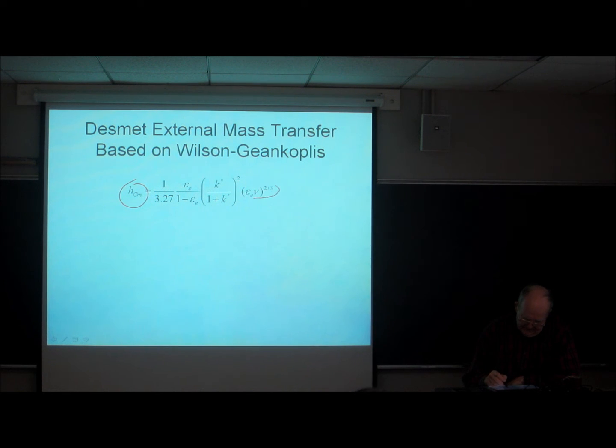And the flow dependence, the velocity dependence is hidden in this term. It works out to be the 2/3 power of the velocity, not the first power of the velocity, because of the dependence of the Sherwood number on the 1/3 power of the Reynolds number.